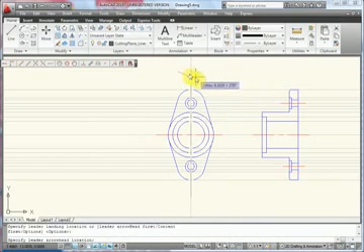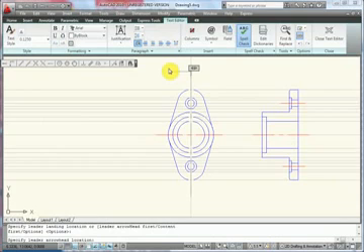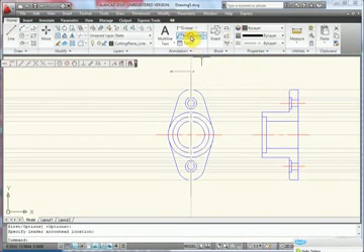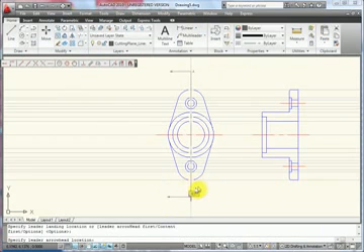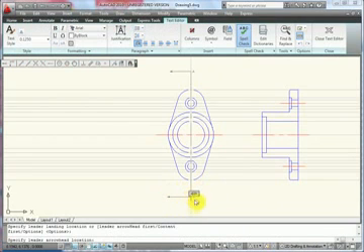So now we're going to select this grip here. Start that over again. I'm going to select this end, and notice the arrow's at the end now, so we want to point in the direction that the cut's made in. Now it'll ask us to specify a letter for the section, so I'm just going to give it an A. When I'm done, we're going to press out in the drawing graphics area. We're going to add one more multi-leader at the bottom, so we're going to snap to the bottom, pull the arrowhead over, and these go out approximately 1 inch as well. And since we gave a label for this multi-leader up here, we don't have to do it down here, so I'll just press in the empty area to end the command.